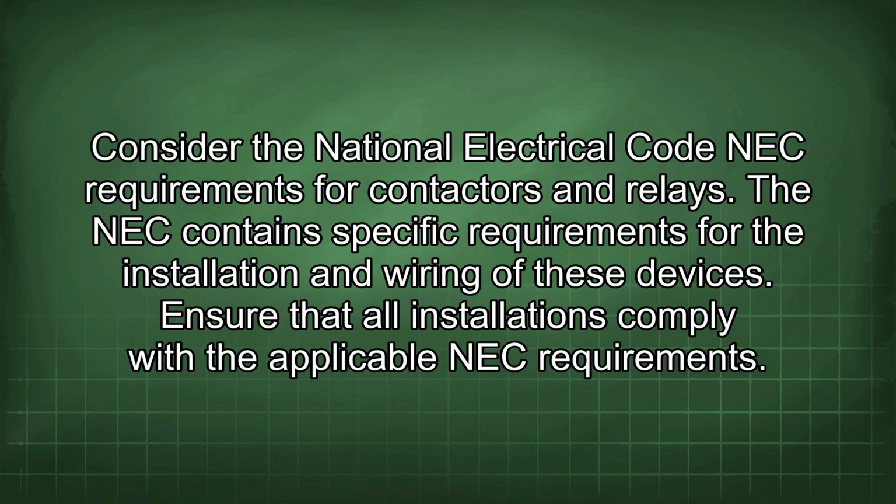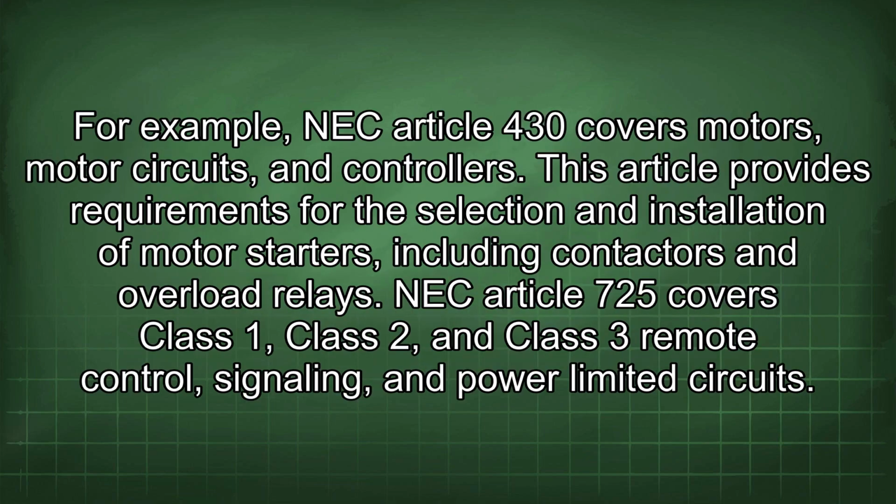Consider the National Electrical Code (NEC) requirements for contactors and relays. The NEC contains specific requirements for the installation and wiring of these devices. Ensure that all installations comply with the applicable NEC requirements. For example, NEC Article 430 covers motors, motor circuits, and controllers. This article provides requirements for the selection and installation of motor starters, including contactors and overload relays.